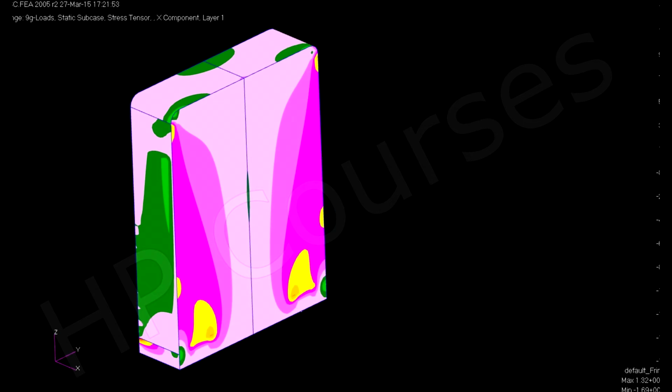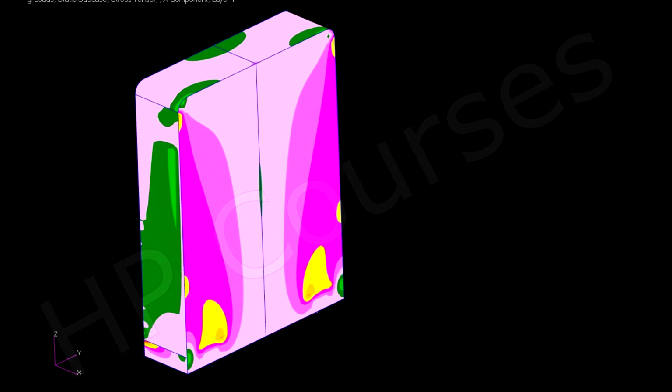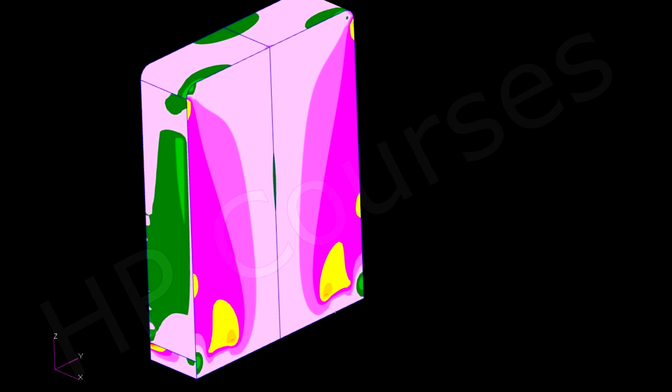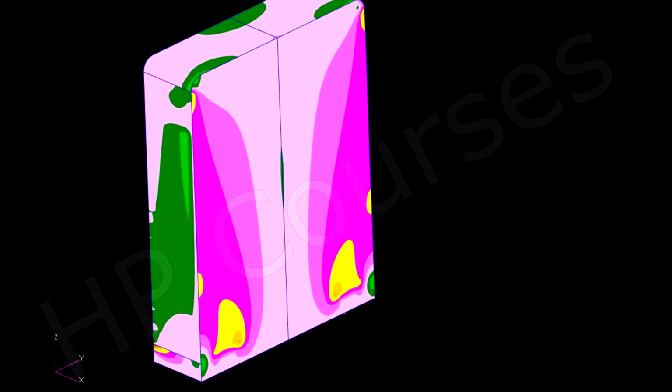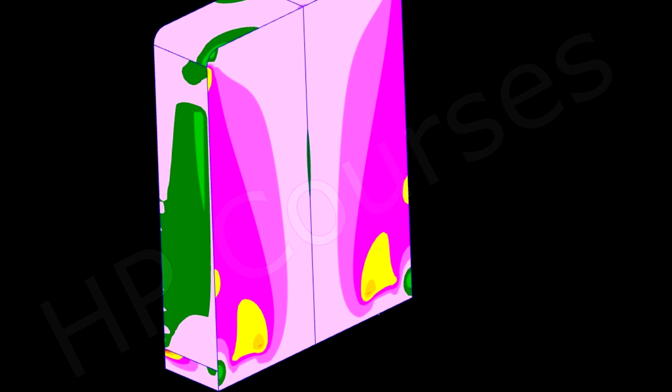Okay, lecture 3 will be next, where we go on to construct a stowage unit. It's important that you understand that the panels in the FEA model will be totally individual, not connected. We will connect them with special connection elements called MPCs, multi-point constraint cards.